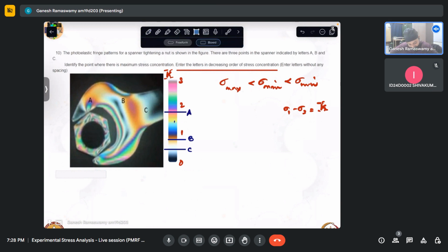So with this, we can infer. Now we are doing this manually. When we do an experiment, and if we have a color table like this digitally generated from a known experiment, then we can directly compare these numerical values, the intensity values, and interpret what this parameter is at every point in the domain. This we will see as the application, the methods in photoelasticity that we use in order to measure, in detail in the subsequent weeks. So this is by comparing the colors.